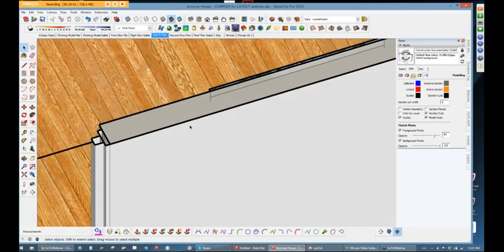The idea behind this in my mind is, in typical drawings that you might do, anything you cut a section through would be typically a heavier line. Obviously, you can change this to whatever you'd like, whatever looks good to you. Even if you make a change here in this SketchUp model and you've already put it in Layout, you can just update the drawing in Layout and it's going to reflect these changes, which for me is the key in using Layout. Exporting to AutoCAD, you're not going to have that opportunity. In Layout, these things are tied together. So SketchUp and Layout are linked dynamically.